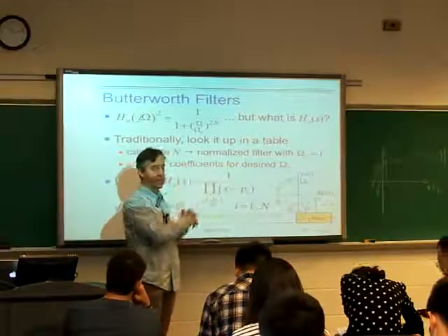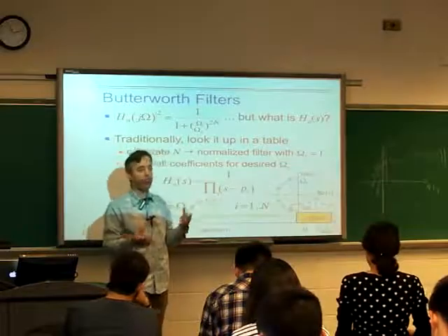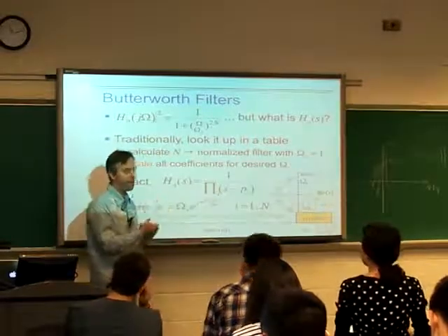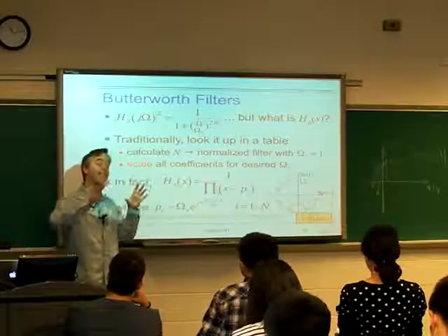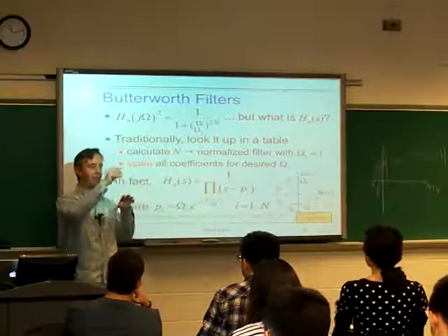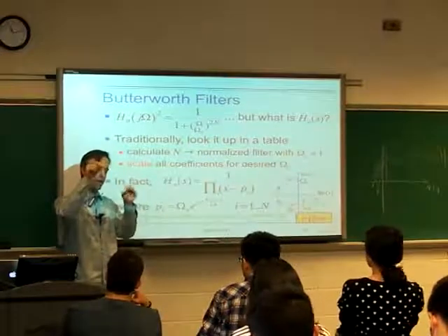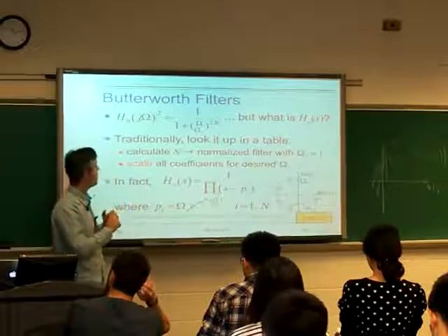You do this process, you figure out your order, you figure out your frequencies, you look it up in a handbook, and then historically you've got some circuit which has some transistors or op-amps, and it just tells you a few parameters, the resistors and the capacitors. You just read the values of those and you set them up.